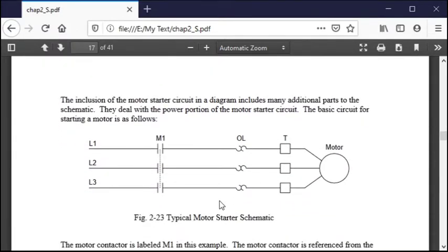So here is a circuit for a motor. The simplest motor circuit you could have for a three-phase squirrel cage induction motor that would start in a factory. I have a contactor for each of the three phases that work off of the same plunger. So you have three contacts, not just one. And these are motor-rated contacts for that particular motor. They're fairly heavy duty contacts. They're not relay contacts. They're motor contacts, but they act the same. You pull in a coil, and these three energize and turn on.